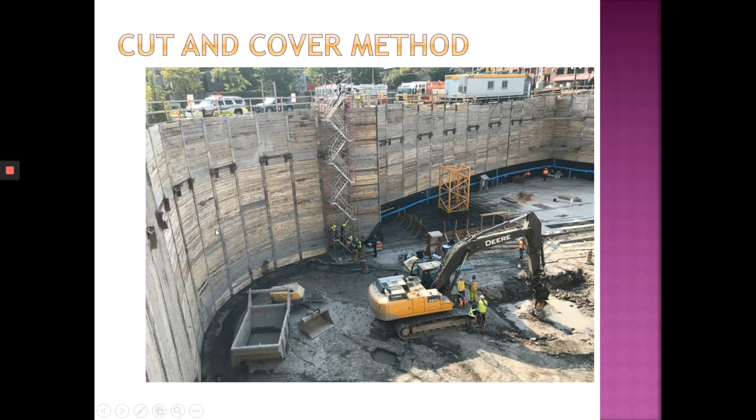Okay, so in this case, the retaining wall actually menahan the soil from that side, from going to this side. Okay, and they have steel structures here. So they don't really need strutting for this technique, right? So this is soldier pile retaining wall.